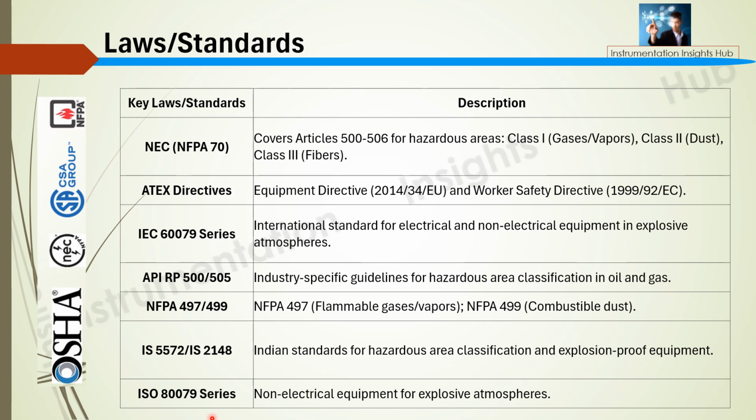So based on those regulations and guidelines, what are the standards? What standards are prepared? NFPA, National Fire Protection Association, NFPA 70, is applicable in USA. The ATEX directive is very widely used. And based on the ATEX directive, we have created the internationally widely accepted IEC 60079.